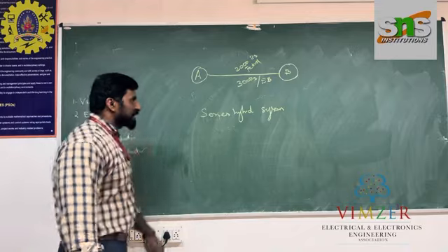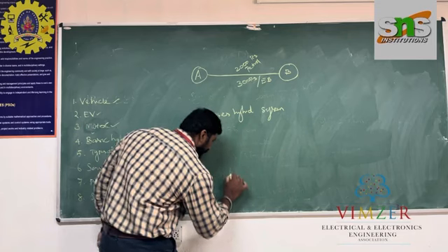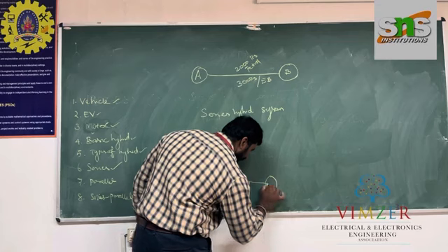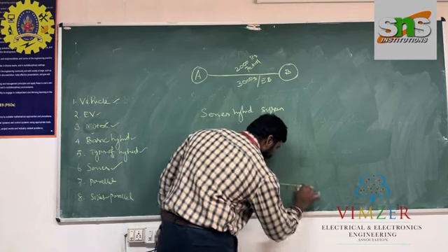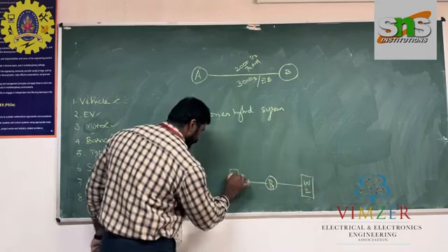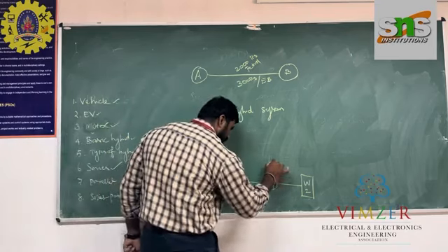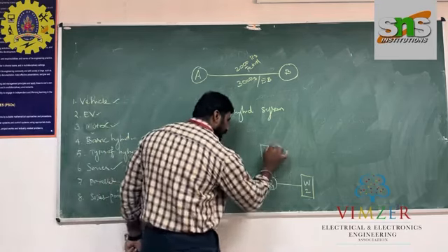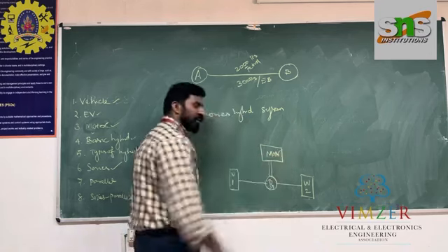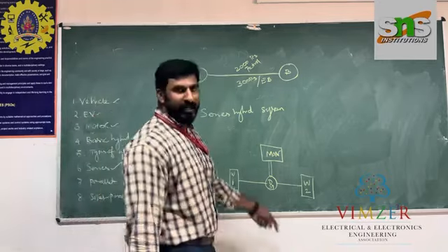First, the series hybrid system, for which we have to make a diagram. These are the wheels. We should start with the outputs. This is the differential gear, and again wheel number 2, wheel number 1. This is connected to a common shaft here. The shaft is connected with the motor. The motor will be the main source for giving the mechanical output.